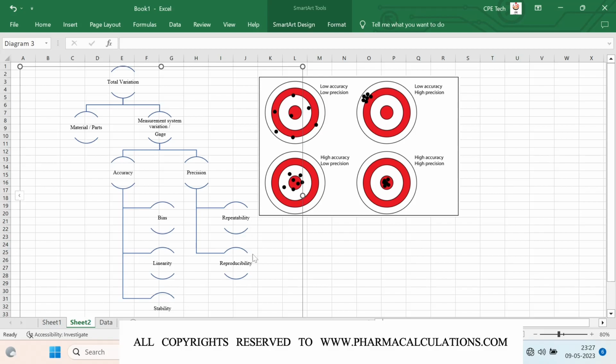So we are going to check this. Why? Because it's all about the abnormality in the measurement system, usually dependent upon the consistency. So we are going to see the repeatability as well as reproducibility. Before going into that, we should understand what exactly repeatability means and what exactly reproducibility means. Repeatability is the variation in measurements obtained with one measurement instrument when used several times by the same person while measuring the identical characteristic of the same part.